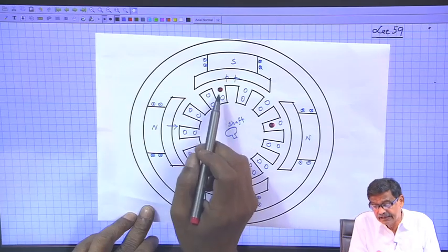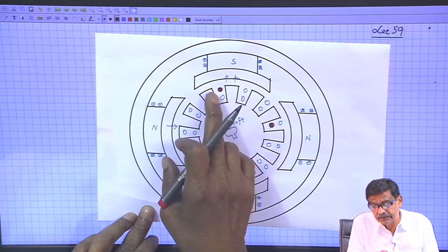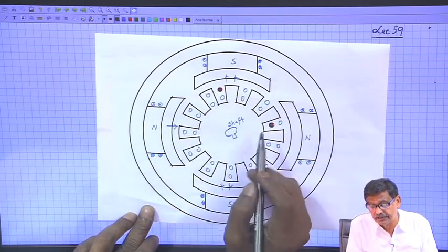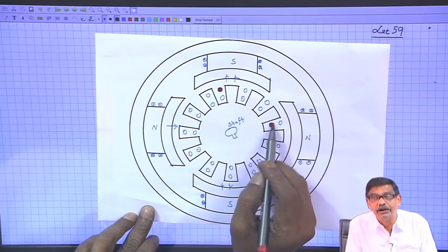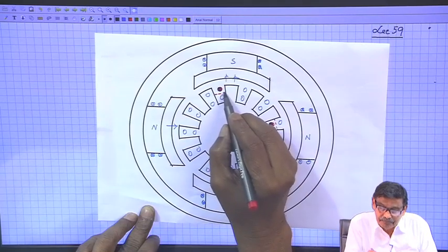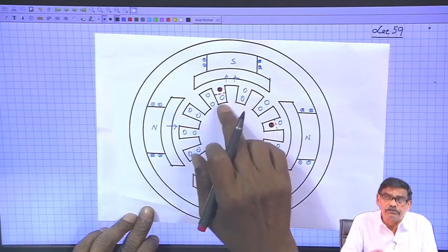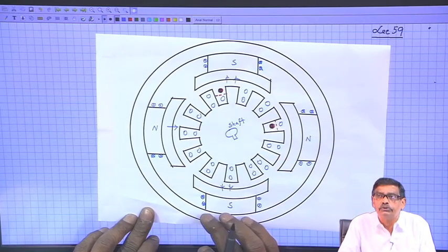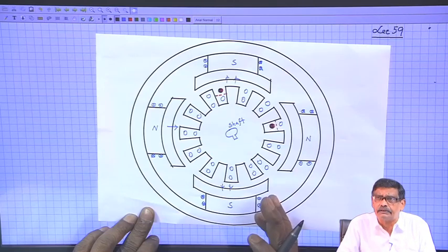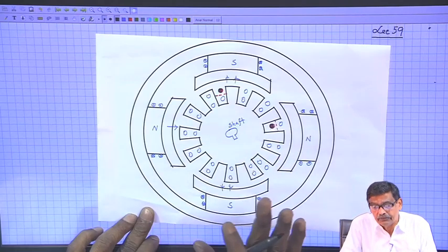We will calculate this. This is one coil side, this is another coil side. That is, it is a coil, this red marked thing, its one coil side will occupy the upper deck of a slot and its return coil side will occupy the lower deck of the slot. That is, in each slot there are 2 decks, double layer winding it is called. Therefore, each slot will house 2 coil sides belonging in general to different coils. We will see how this will be nicely filled up, that we will see later.